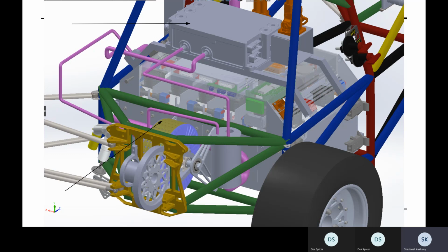Liquid cooling would require some kind of fluid conduit, either along the cylindrical surface of the cells or the ends of the cells. That's very ungainly, or it was very ungainly when we first conceptualized it. So feasibility is the primary driving factor, I'd say, in air cooling. With air cooling, you can get a more consistent cooling across the cells, whereas with liquid cooling, if you just did them at the ends, you get the cells cool at the ends, but towards the middle it's a bit harder.